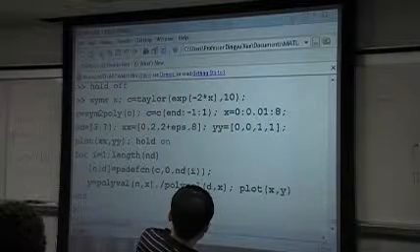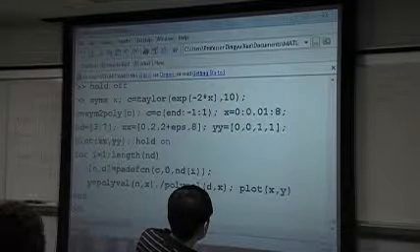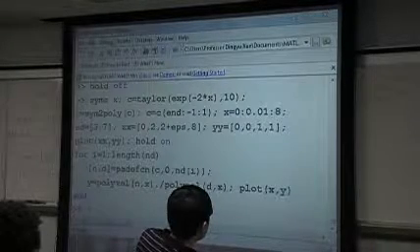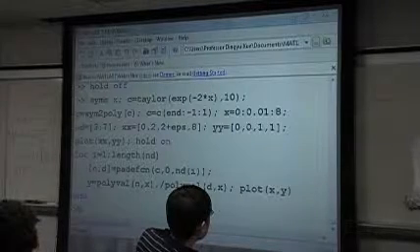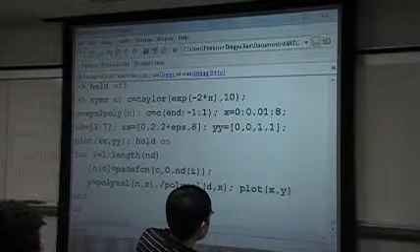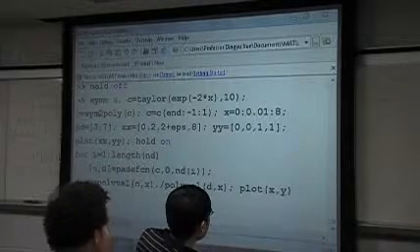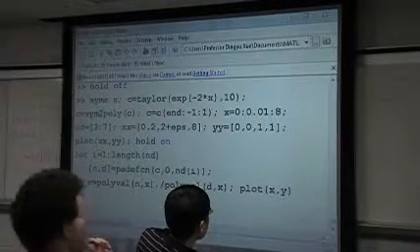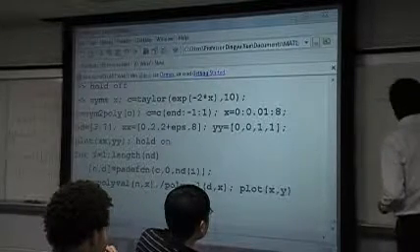Padé approximation is always very useful, especially in delay control systems. So I will explain more here. Suppose there is a transfer function of the original model without a time delay, and here is a time delay, and here there is a Gc controller.